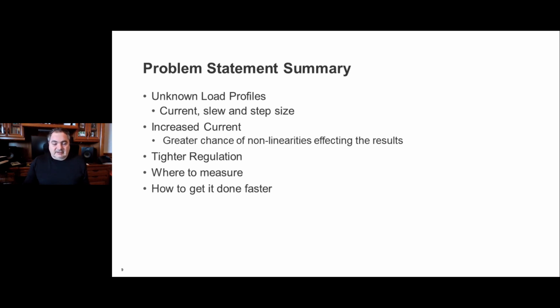There's diode emulation and there's power saving techniques that every architecture implements. And of course, every vendor has slightly different ways of implementing these architectures. So there's different things we need to be looking out for, and we don't know quite how exactly they're going to react. So the increased current offers a lot of potential for some peculiar corner case activity that we're not going to be aware of until you actually get that product and you're actually slamming the rails itself.